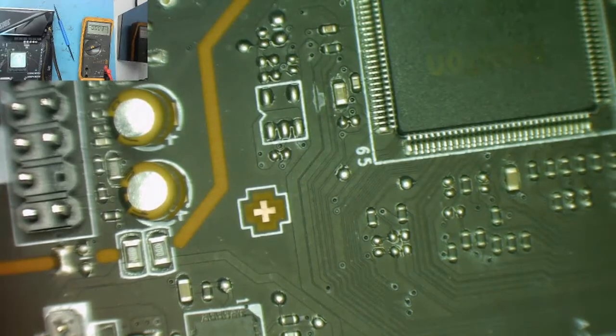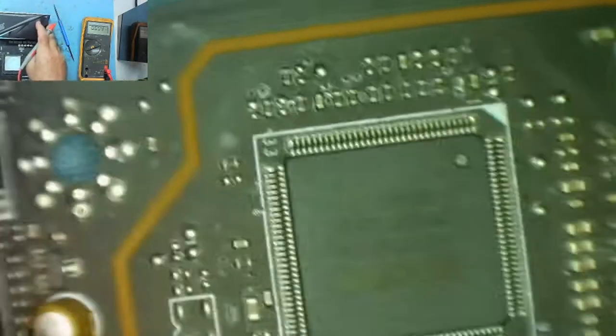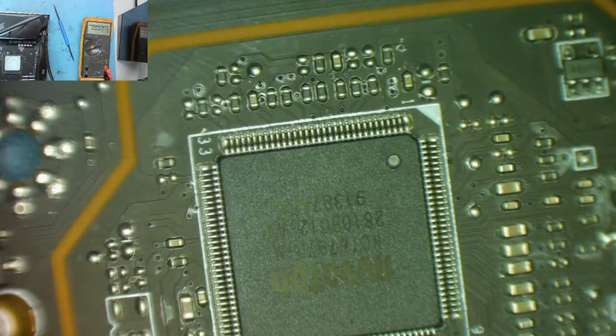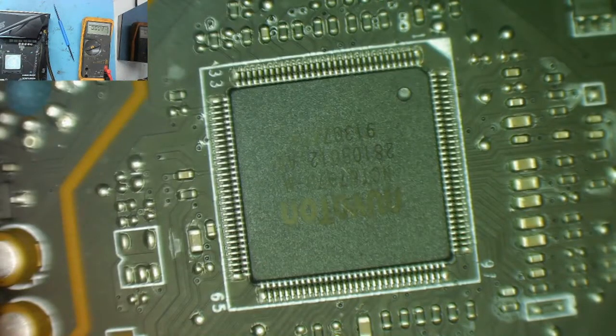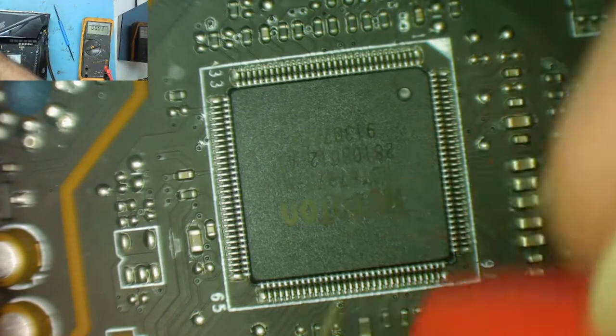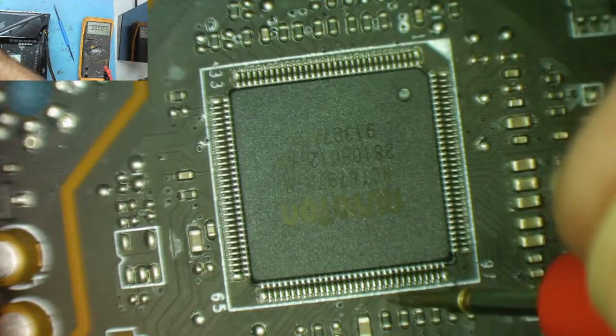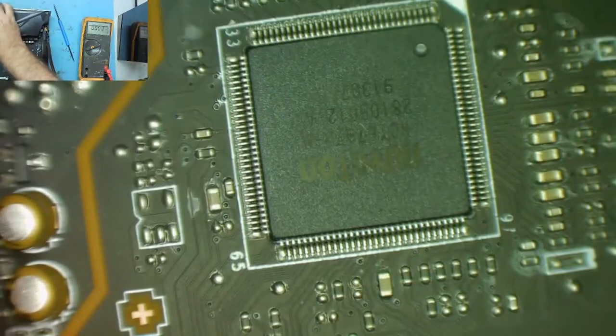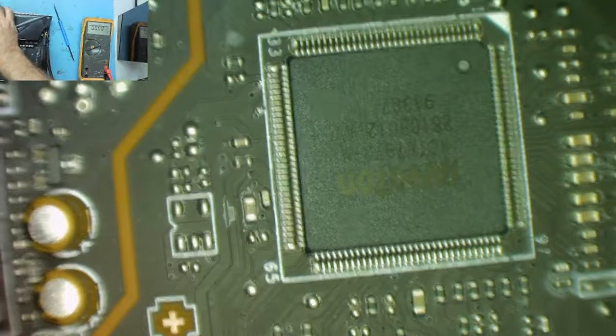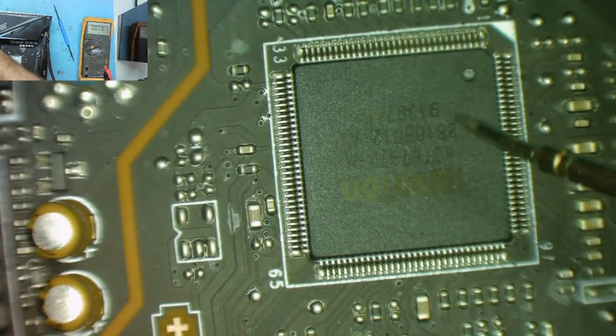Right. Somewhere on this board that has been dropped down to 3.3. I could probably have a poke around and find out where it is, but I'm not going to. I'm not bothered, because I know there's 3.3 on the on-off switch, so I know that's working. What I am interested in is whether there's any 3.3 volts over here. The first place to look is going to be on capacitors, because if it's on the capacitors, the chances are it's on the pin, without me looking at the datasheet for this.